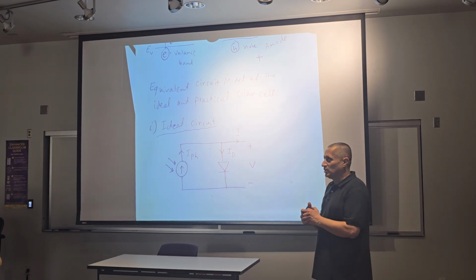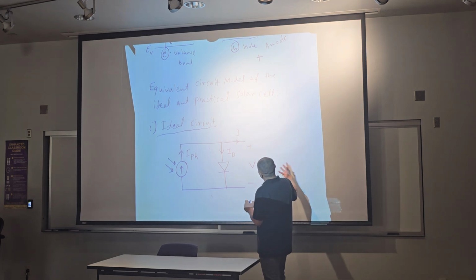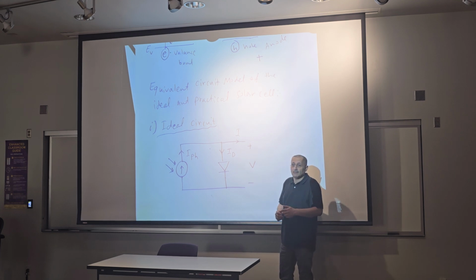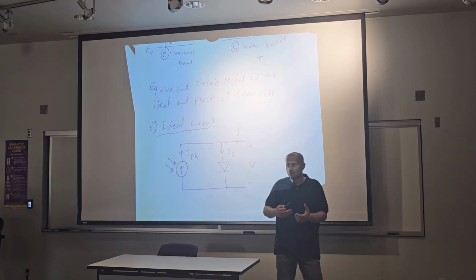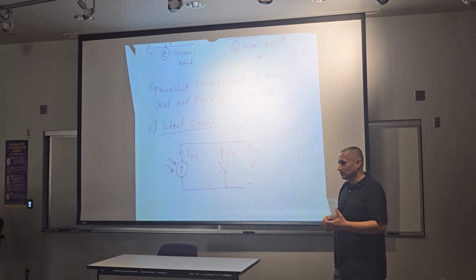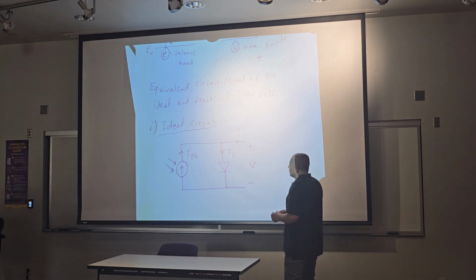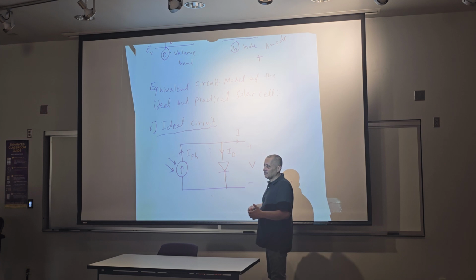If you have a DC load, okay, maybe you will connect the DC load directly to this, or maybe you need more voltage, so you should connect a step up or boost converter, DC to DC converter, or maybe you need high current, low voltage, so connect a step down.